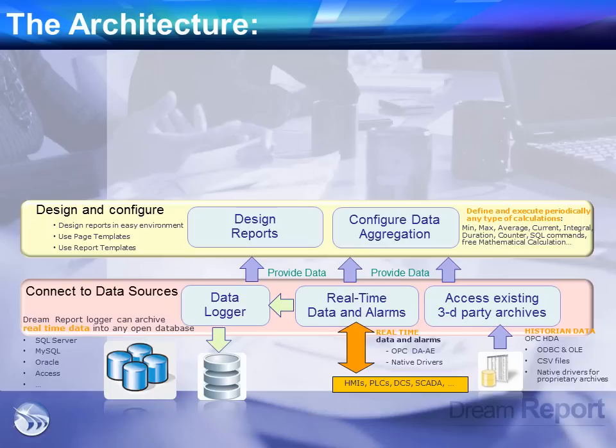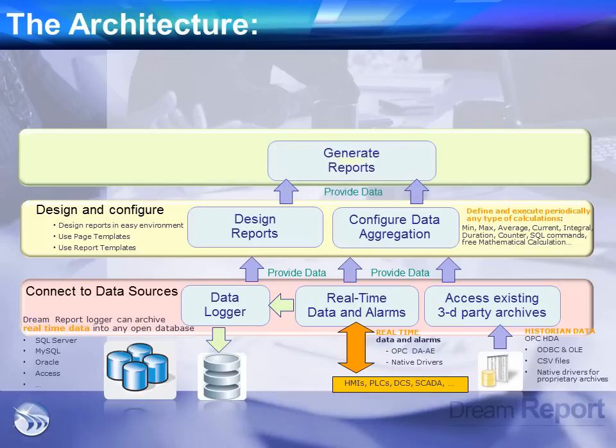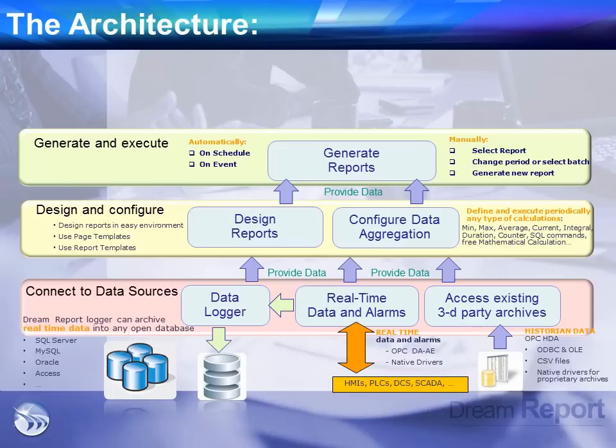Another good thing in Report Designer is the ability to use report templates. If you have a typical report which can be used in many projects and you don't want to spend time to design it again and again, you can build such a report only once, save it as a report template, and then every time you need such a report, you just make a new blank report, load the ready report template, select data points for the new report, and the new report is ready in a few clicks. That saves a lot of engineering time.